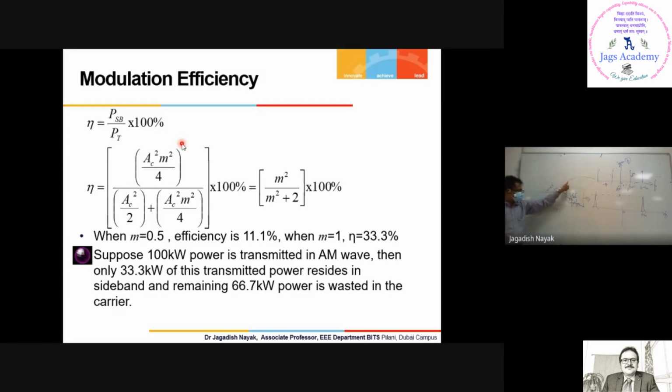So this is the spectrum of the signal which is available here. Now the transfer function H(f) is this one. Now what is the output? It is the multiplication of the spectrum of this by this. What you get as the output here is the filtered signal in the frequency domain. Now how do you get into the time domain afterwards? Take the inverse Fourier transform, and you'll get the time domain. So that is what your signal is. That's what your single sideband AM wave is.